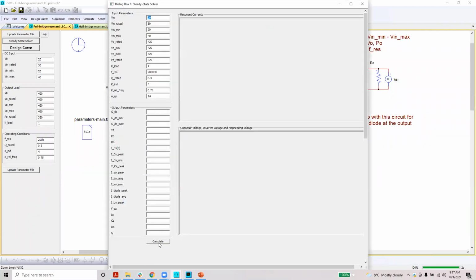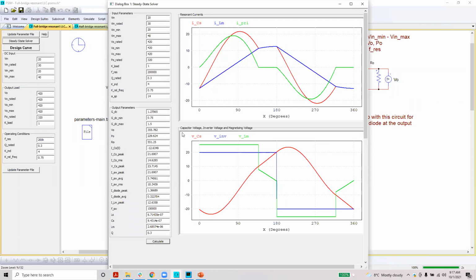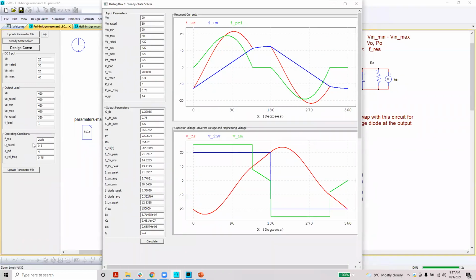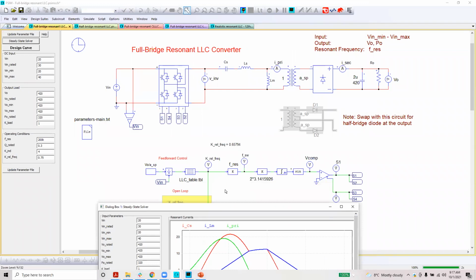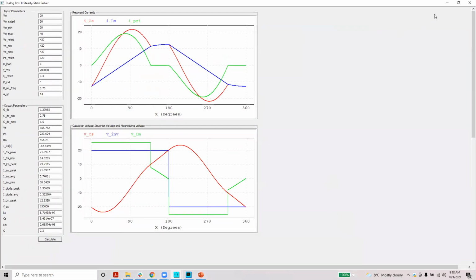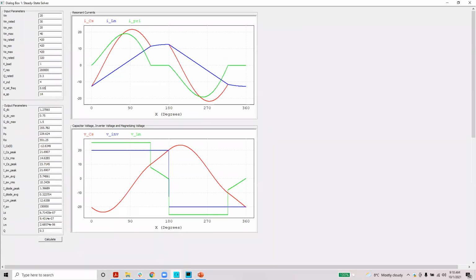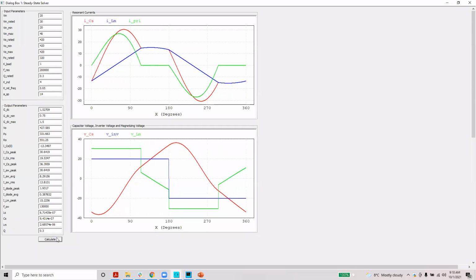So this tool is again the time domain based tool, and if I run this, by default it will run at 0.75. If you want to check at your 0.665, this is the same as this. All your parameters are like this. So this is an open loop. Now, since because of the lookup table you have found out that this is your frequency, you can use this to check it, right? So let me just put 0.65 or whatever that was, right? So you can basically check at 0.65 you get the 1.5 gain you wanted.